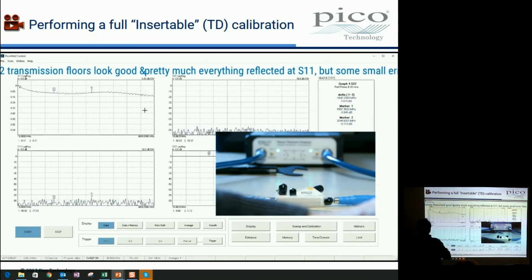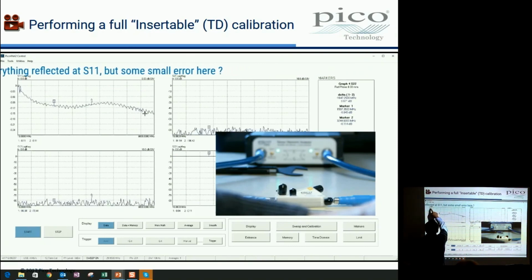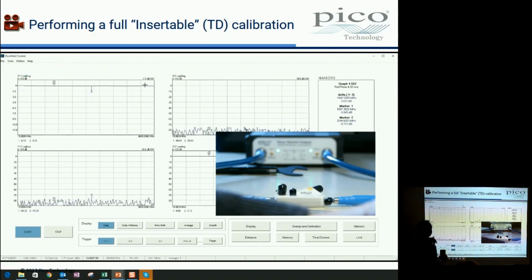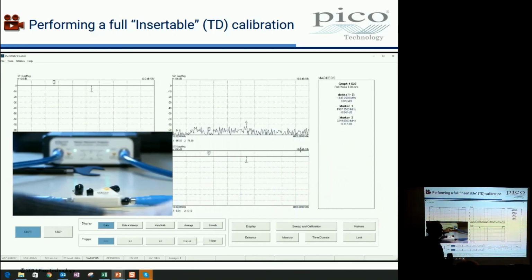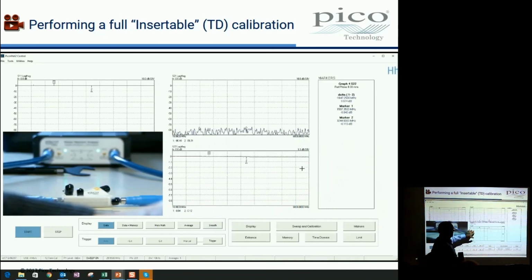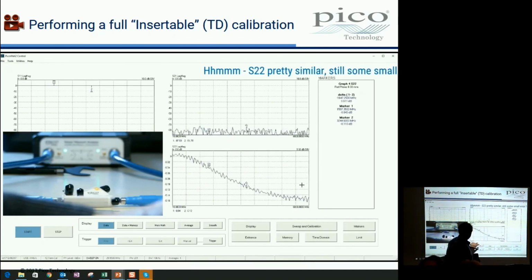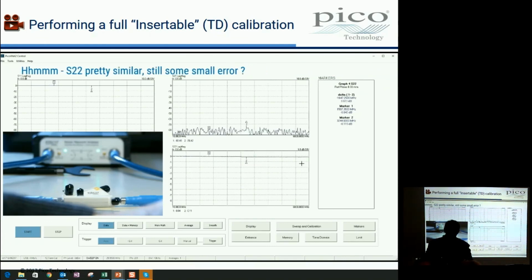All right, now here you see I've pulled this down, and at high sensitivity I have got some reflection. It's a short, so I should see a flat line, shouldn't I? No, because it's not a perfect short. Likewise over here, I'm going to pull this down, and I get something that looks pretty good. We're only talking about 0.16 of a dB.